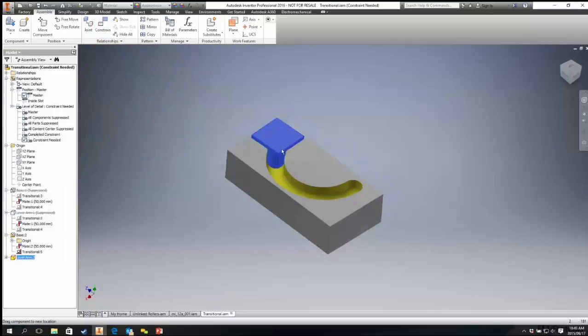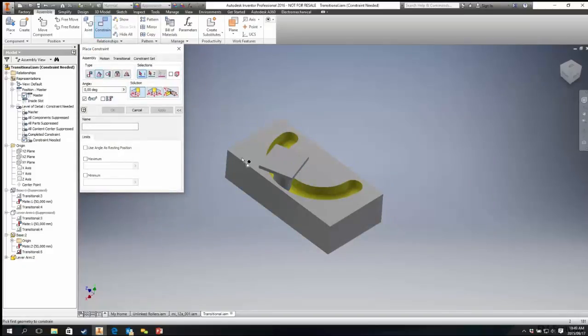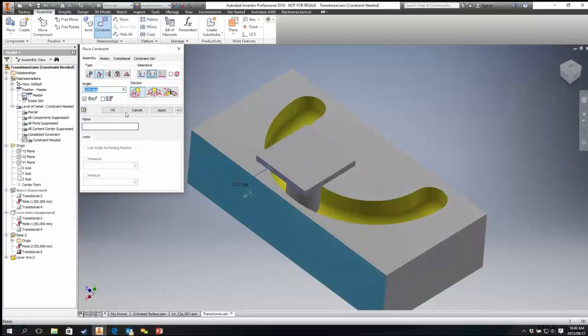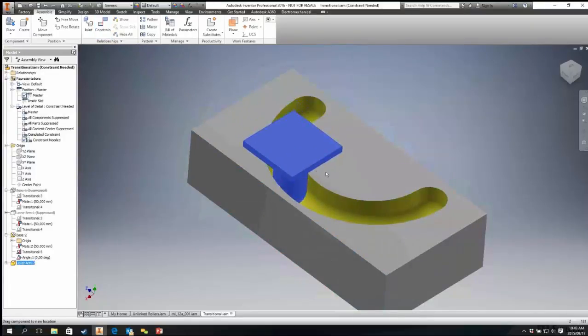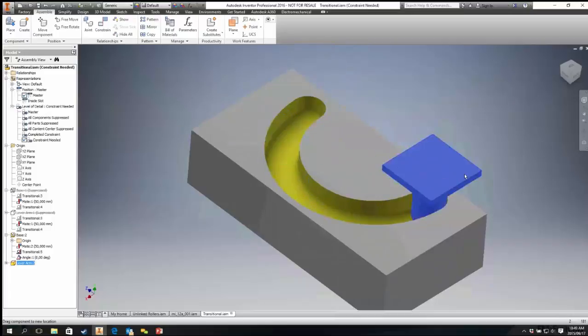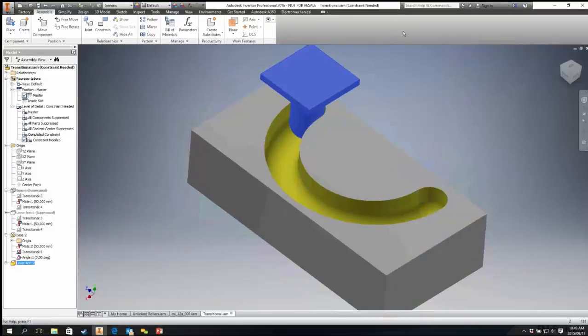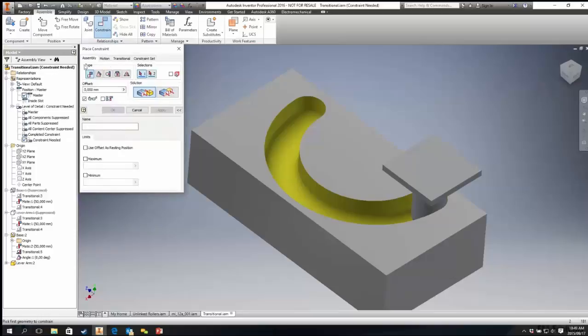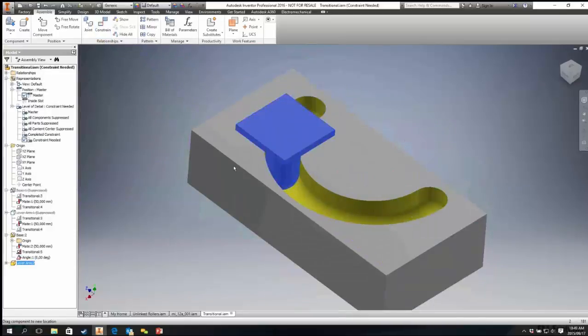Okay, you can still add in your constraints if you want this to always be perpendicular to this face or flush with that face. We can still put an angle constraint to make sure that takes place. Okay, because now I can move freely, but it always has to be flat on that face. So you can see it can't move out over there. So with translation, that was the alternative that we also had over here within the constraint tools, motion and translation, which allows us very nicely to model something within motion, to specify exactly where it can travel from and to.